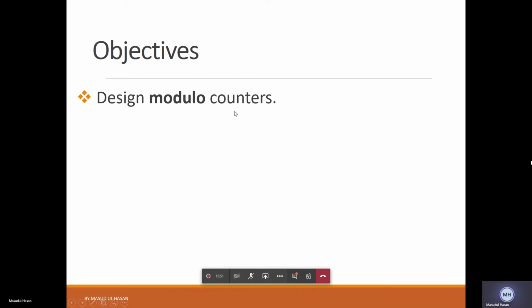So this thing is called clock gating. Clock gating means there are gates in the path of the clock. Like this is the path, this is the clock, then it is coming from this Q, then this clock is coming from this Q, and so on. So there are gates in the path of the clock. This is not allowed. In some special conditions, you can use it, but this is not a correct engineering approach. It will make everything out of synchronization.